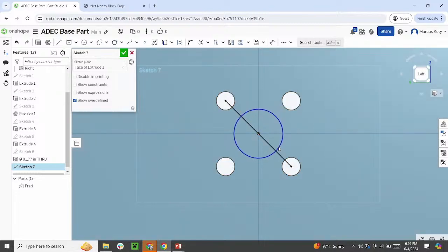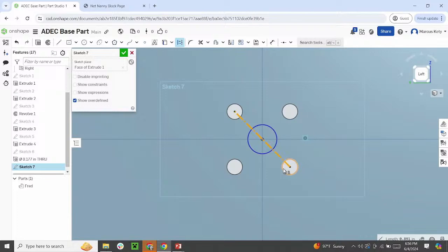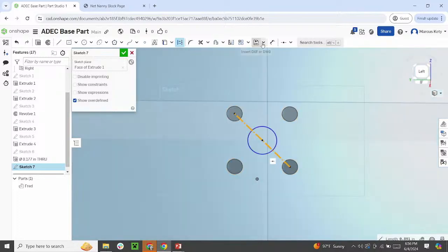Claire, do you still have it pulled up? What is the shaft diameter? 8 millimeters. 7 millimeters flat to flat. And what is the overall diameter? 8 millimeters. So it's an 8 millimeter. I'm going to give it some clearance. We'll say 8.5 millimeters. And we will hit.